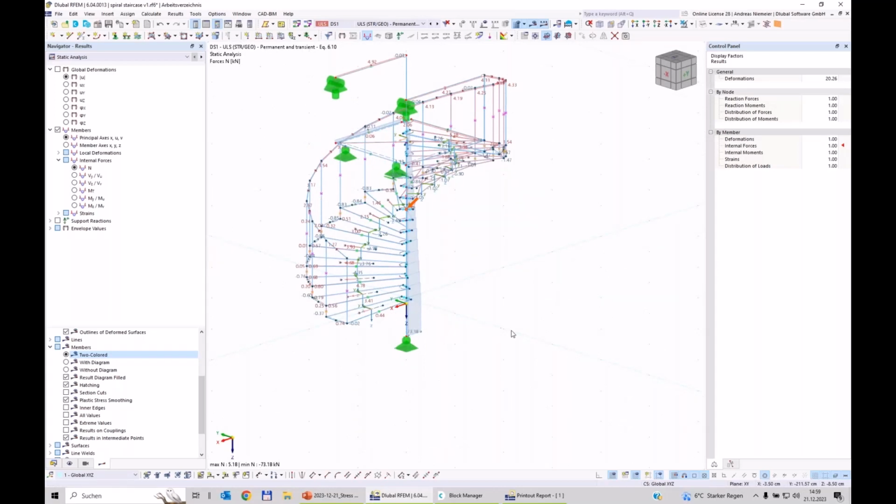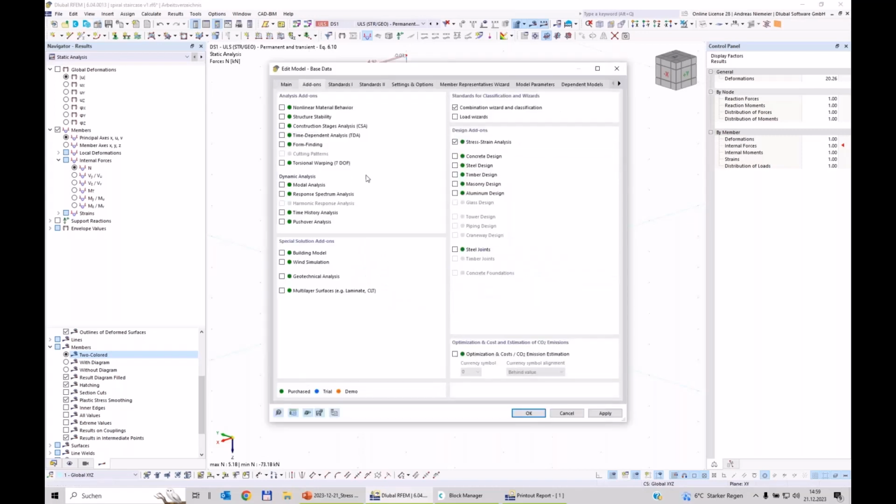And I calculated the eigenvalues, and it has buckling values bigger than 10, so it's not a problem. But to check it, I can offer the structure stability program to check the eigenvalues, or to use the steel design program. So if it's needed to make a further check, the program offers you to activate it. We can say, okay, please make a steel check.